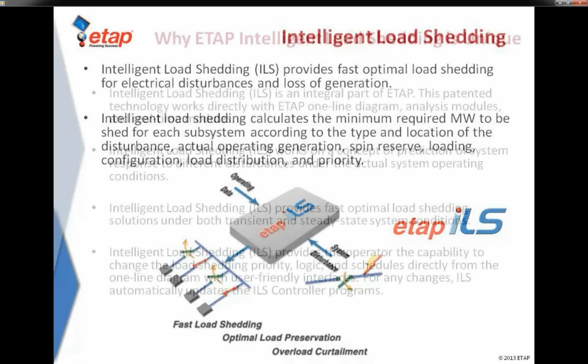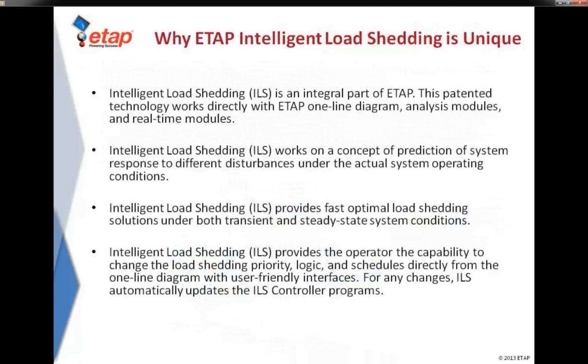The most important benefit of ETAP-ILS is the load shedding validation. With the simulator, ETAP-ILS recommendations can be tested and analyzed with the design team before ever taking the system online in the field. Both steady-state and transient conditions can be simulated to analyze intelligent load shedding system responses. This technology is currently used with many other third-party ILS systems to validate the logic that has been written for those systems. Whereas with ETAP-ILS, you could use the same tool to validate and configure and operate in real time.